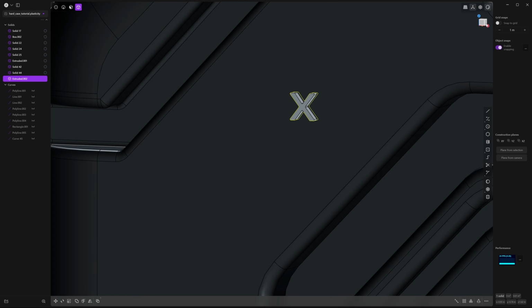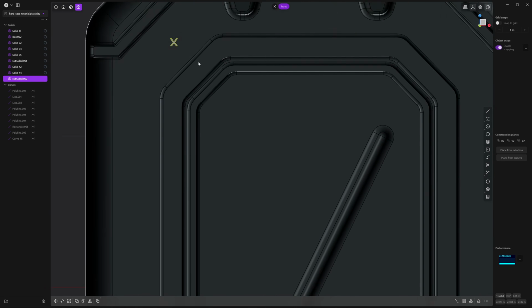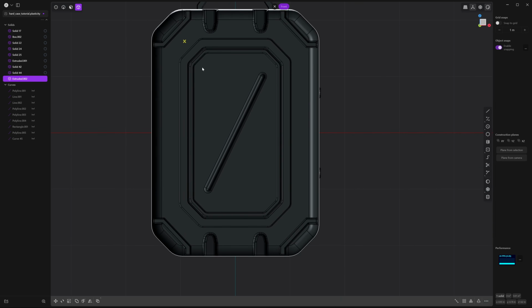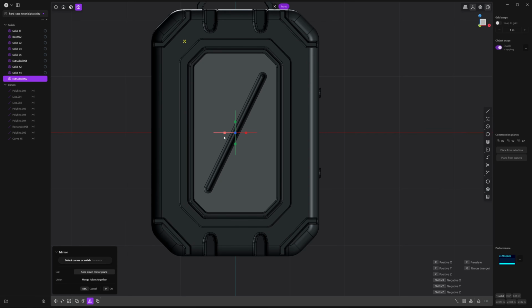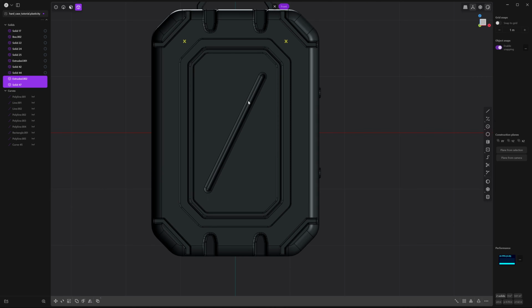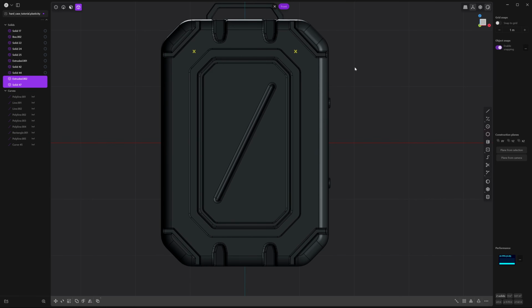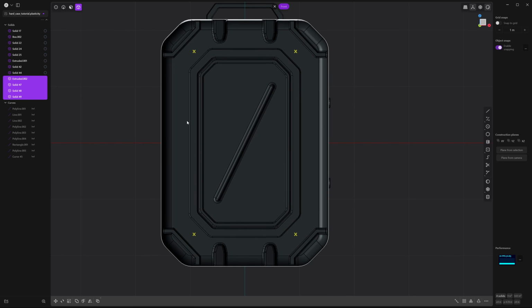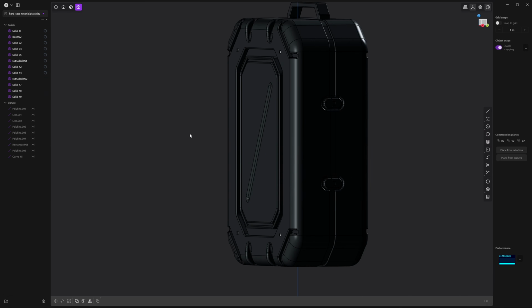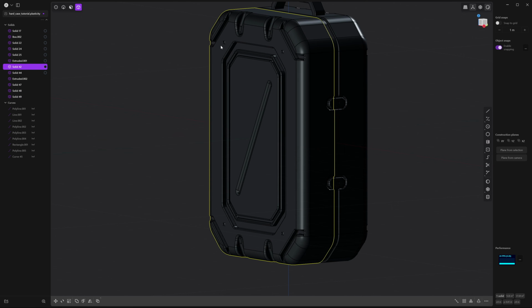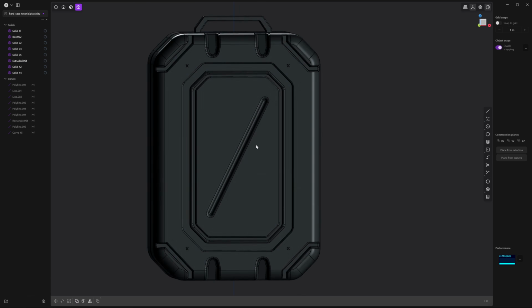And let's go to the front view. And we're just going to mirror all of these over here. So press Alt X, mirror down this red side. We'll right click to accept. And with both of them selected, press Alt X once more, and then this time on the screen axis. So you should have 4 now, which we can use to Boolean. Select your main body and select these 4 new X's. Press Q and right click to accept, and now we have a little bit more detail.